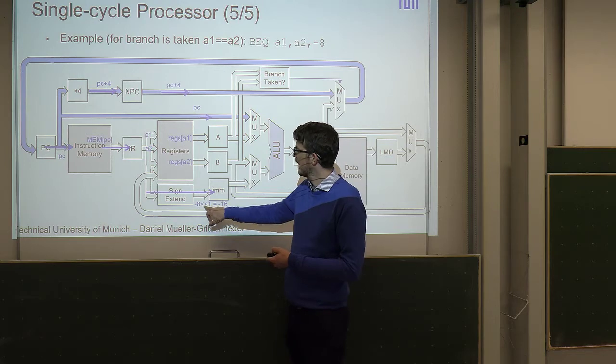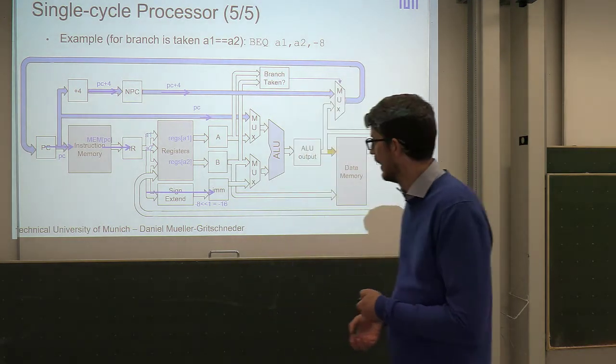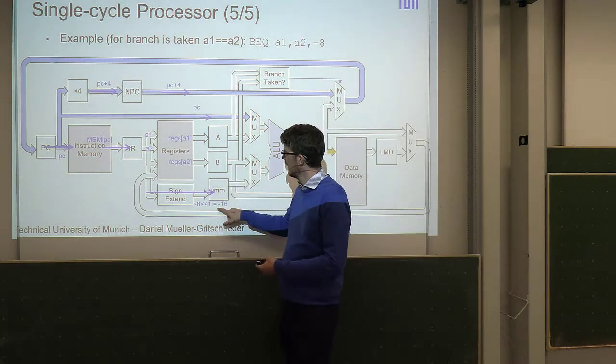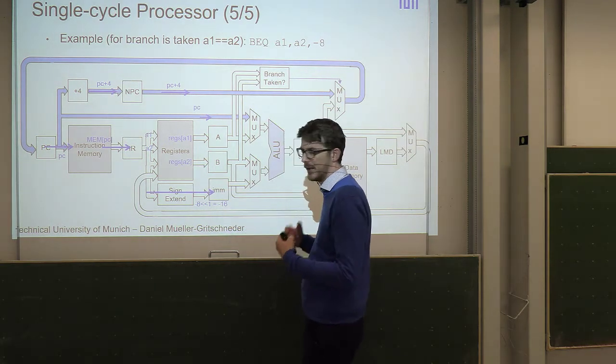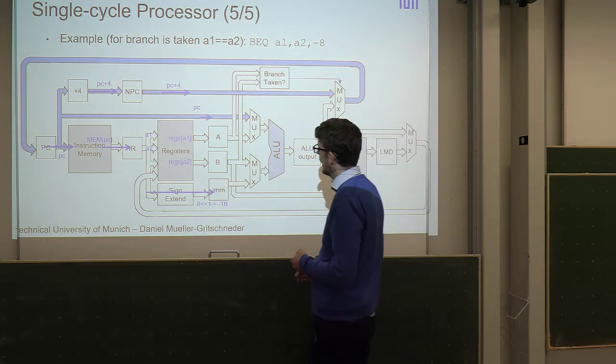this offset actually gets a shift by 1. This is just defined in the RISC-V ISA. So the actual offset is minus 16, so we want to jump basically 4 instructions up again, right? So minus 16. So it could be a loop, right? Where we're jumping 4 instructions up again if it's equal.